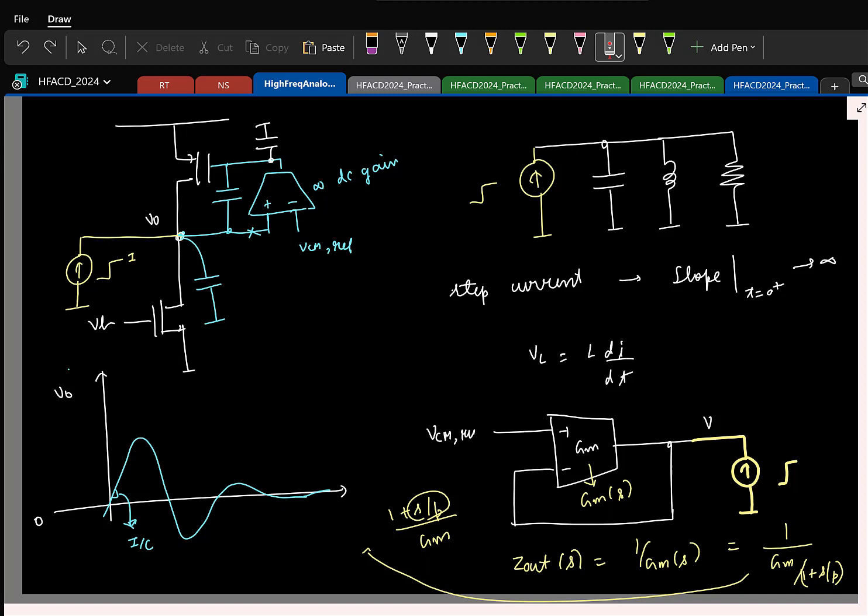But the characteristic you modeled using an inductor. Correct. We could model it using a second order underdamped RC only. It's a model, right? You can do anything, but this is the simplest model. If you have a second order RC, it might not be easy to do, but this is more straightforward. Even if you do it with a second order RC, you will find an inductive behavior somehow, because the output resistance increases with frequency at some point, and the simplest model is an inductor. So this basically captures the effect of inductance.